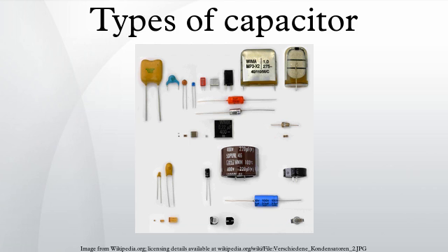For some capacitor types therefore the IEC standards specify a second temperature derated voltage for a higher temperature range, the category voltage. The category voltage is the maximum DC voltage or peak pulse voltage that may be applied continuously to a capacitor at any temperature within the category temperature range. The relation between both voltages and temperatures is given in the picture right.